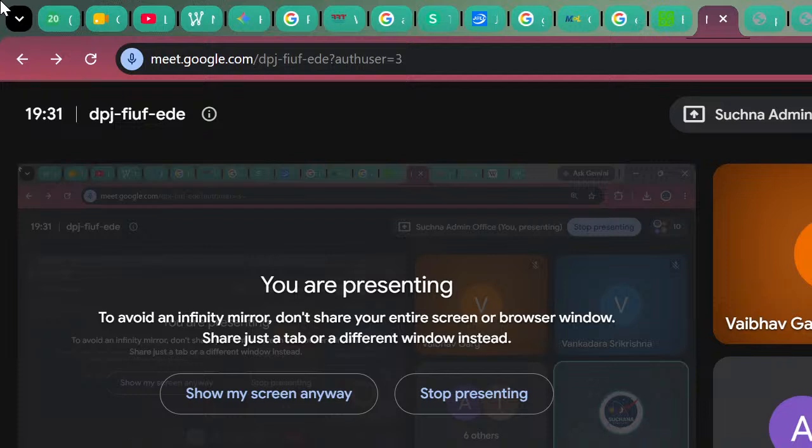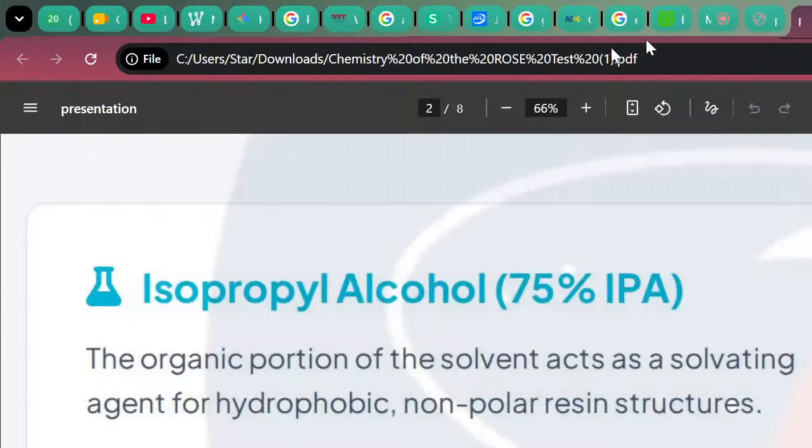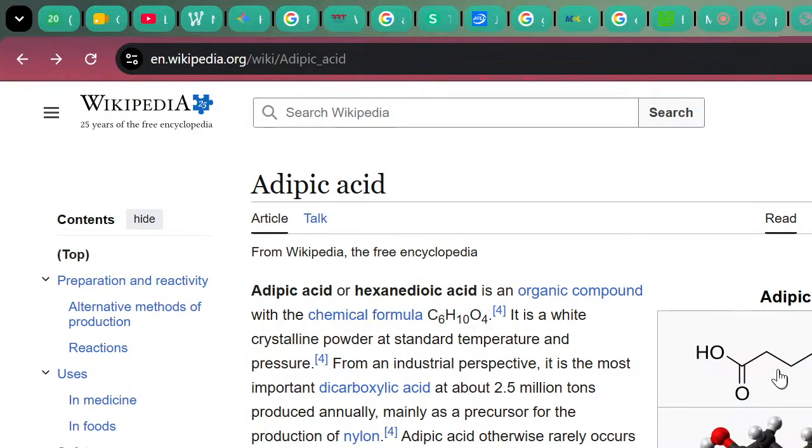So we need to get rid of this metal oxide layer. To remove it, adipic acid is used as an activator, which removes the metal oxide, and therefore the bare metal, the actual metal, will be exposed, and we can do the soldering. That's why it is called an activator in soldering. This is actually part of the flux. These activators are used to remove the metal oxide layer to make soldering possible. But sometimes there would be remnants, that means additional adipic acid present.